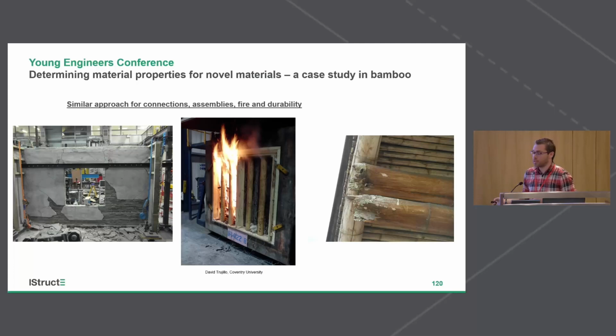Same for the trailing stud. One can do the same for tension. So again, you can remove certain failure modes to force a failure mode which we really need to test. In this case, this was shear. So we tied the panel down, we forced a pure shear failure mode, and that's covered in some of the testing for shear walls, and that way we're being very efficient with the testing that we do.